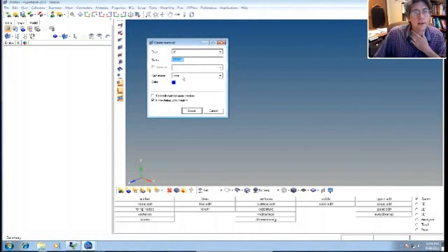Since we're in the Nastran user profile, you can actually pick from the various Nastran material cards. Now we've only used Mat 1, so we'll define a Mat 1 card. So you can see it knows the different Nastran materials. If you had it set to Abaqus, you wouldn't see Mat 1. You would see whatever selections are available for Abaqus.